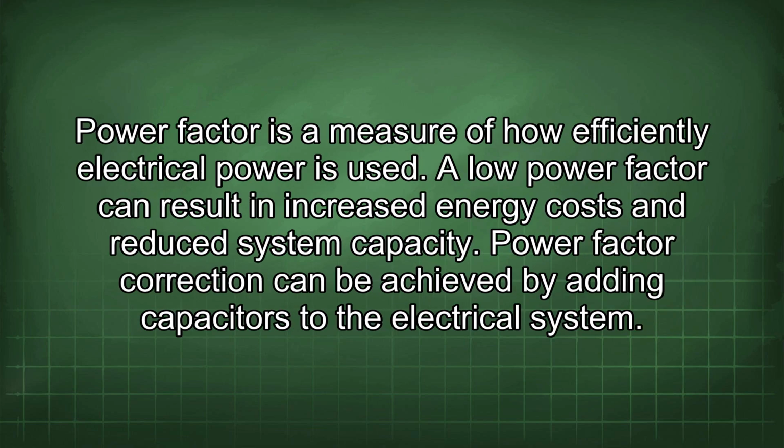Power factor is a measure of how efficiently electrical power is used. A low power factor can result in increased energy costs or reduced system capacity. Power factor correction can be achieved by adding capacitors to the electrical system.